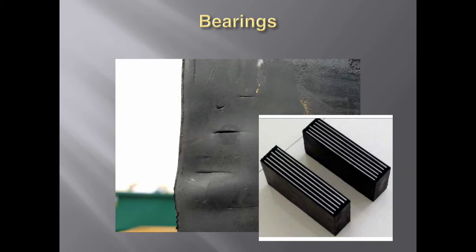So you can see somebody got a little excited with the hammer and beat the ends of the bearing up, and once they do that, it will fail, because not all the metal plates are stainless. Sometimes we'll have just regular steel in there, and if that's the case, they rust, and then they will lose the bond once they start breaking down.